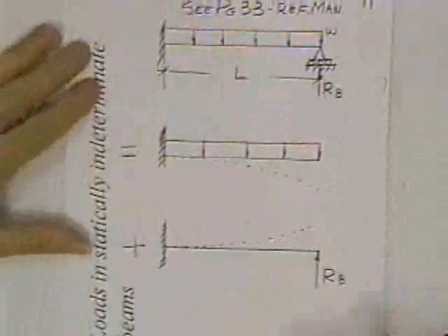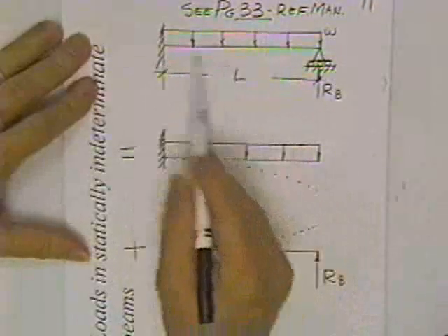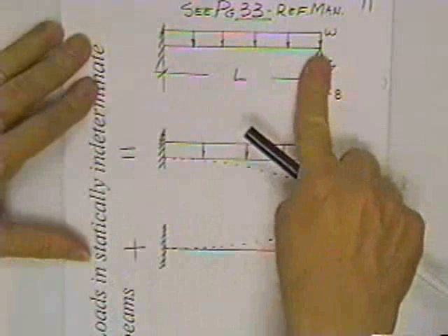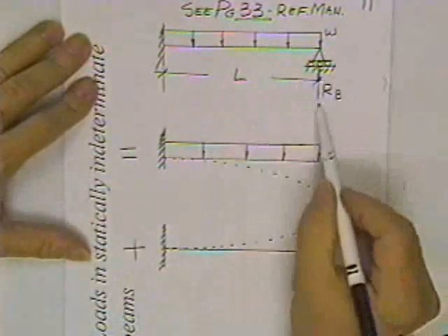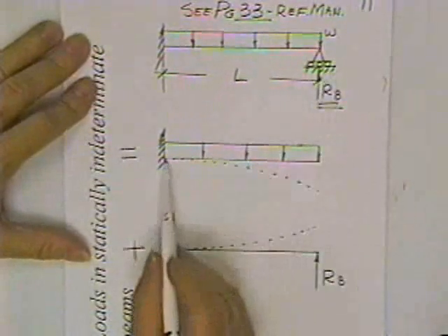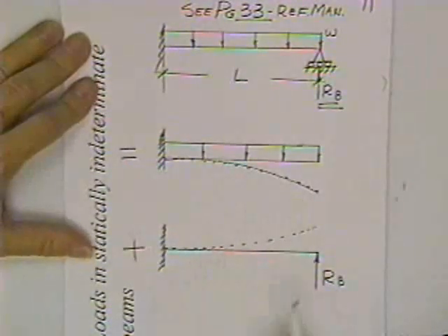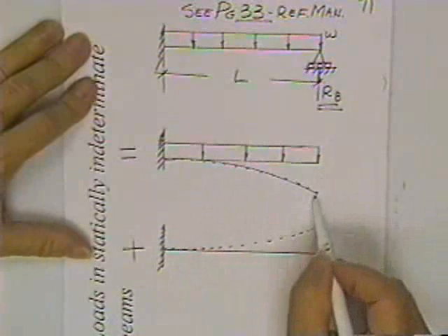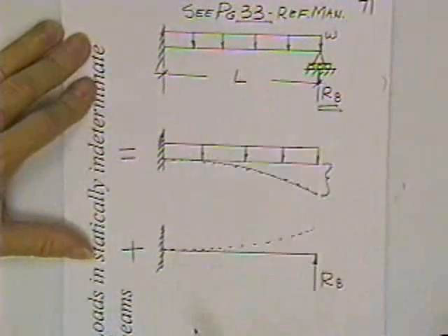Finally, if you look on page 33 in the manual, if they give you a beam that's a cantilever beam, you can solve for everything in that cantilever beam. If he props the end up with an unknown force, statics alone won't do the job. Take that off, let the beam deflect like it wants to, even though the boss will really be hacked, because he didn't want it to deflect on that end, and solve for this number from page 33.